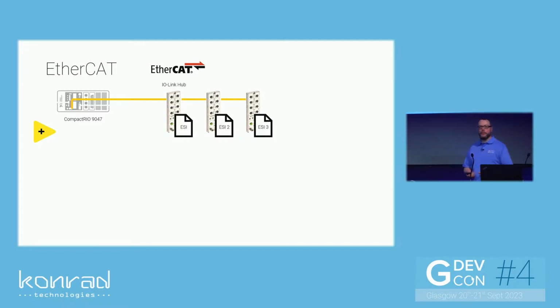Tip, if you've got multiple devices, now if you put 3 of those Beldens on, or the IFMs, they're not going to be connected to the same IO-Link sensors. They're going to be different. So they need a different configuration. If you've modified the ESI file to specifically say, I've got these devices on these 8 ports, you need a different ESI file for the next one, and a different ESI file for the third one.